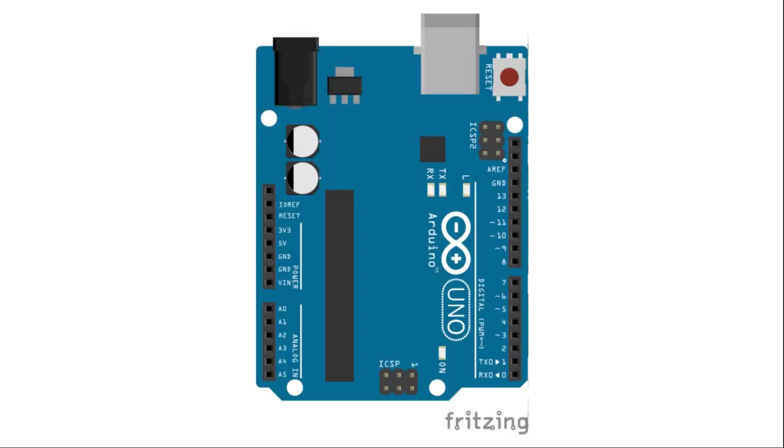On the top left corner of the screen, where I am pointing with the cursor, we have got the power input. This is to be connected to an adapter, but beware of the allowed voltage. The standard is between 7 volts and 12 volts. I use 12 volts comfortably.